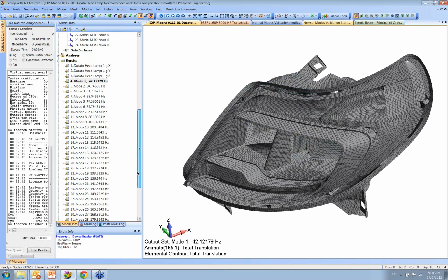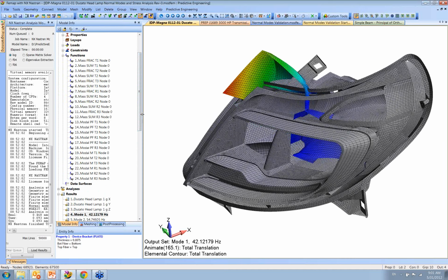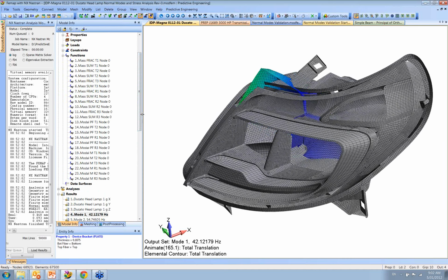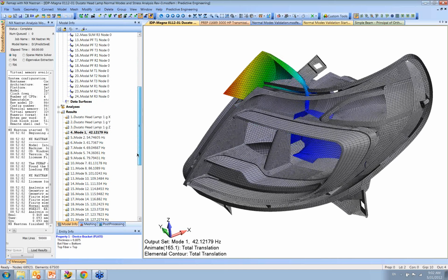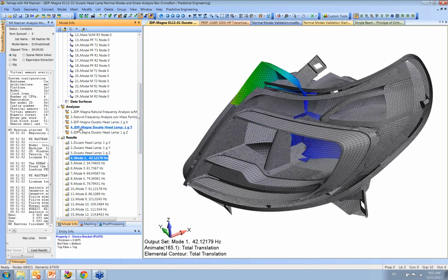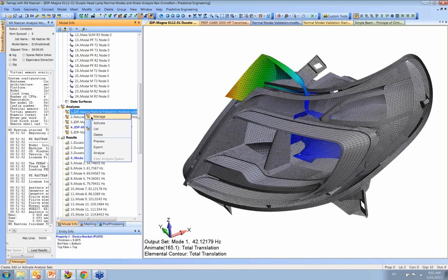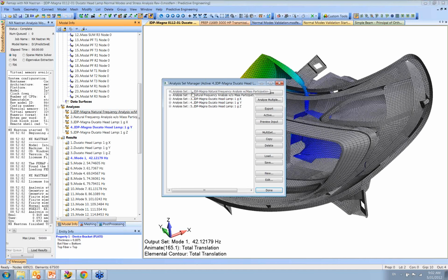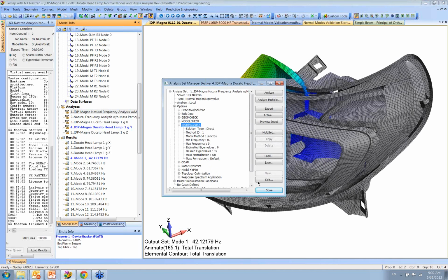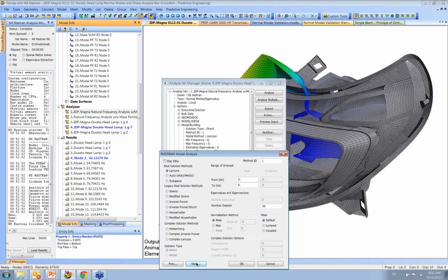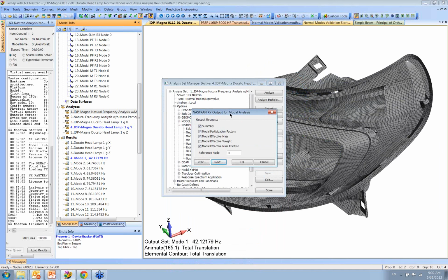So you get your frequency range here, but it doesn't tell you the relative importance of each frequency. It doesn't tell you which carries the most mass and what is doing what. So this is where you request it to dump out the mass fraction, without mass participation and with mass participation. So let's go there. Options, modal buckling. If you guys have done any vibe work, you're going to see this come up.